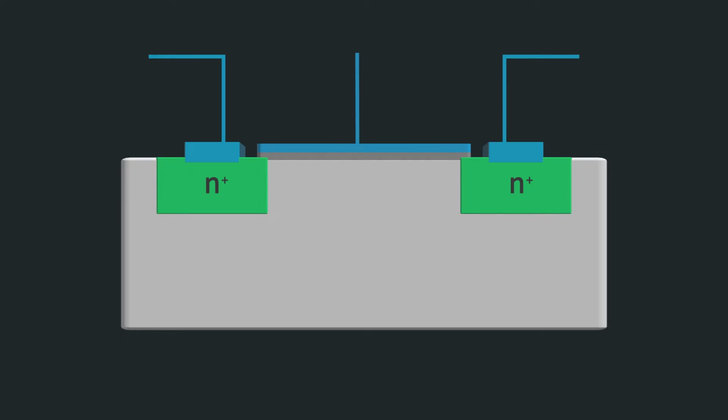As we know from our studies about diodes, at a p-n junction, a depletion region is naturally created even when there are no electric fields. This is the natural state when the gate voltage is 0 and the MOSFET is operating in the cutoff region. This is an operating region, not a physical region, which can be confusing.